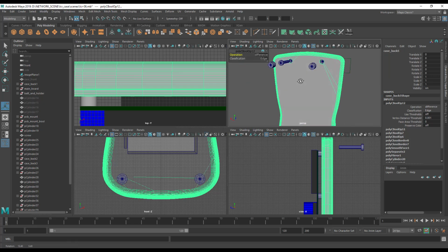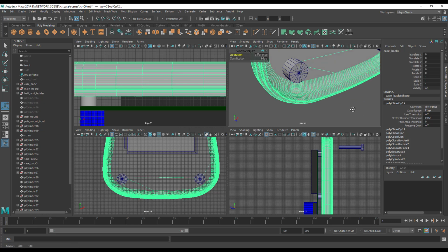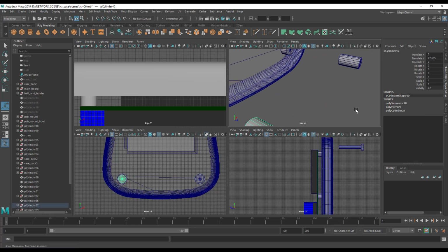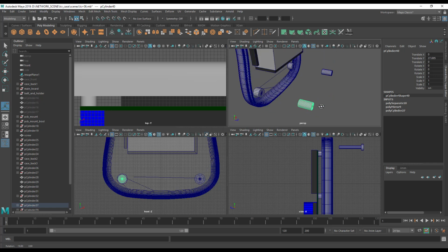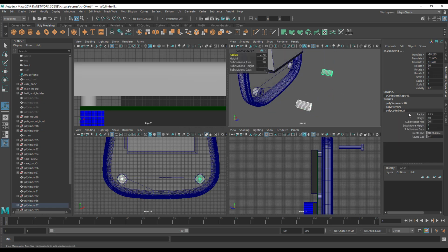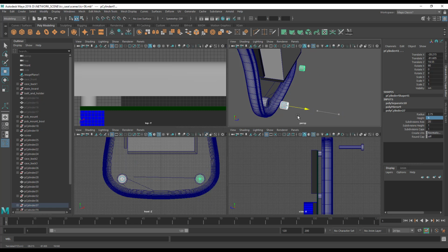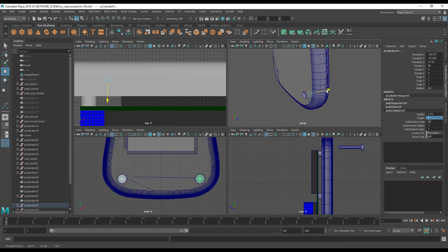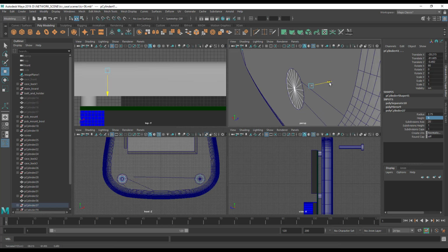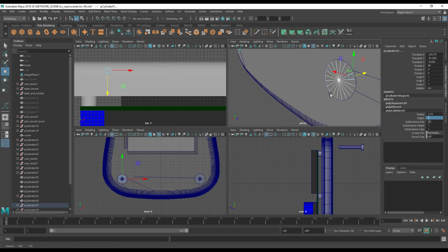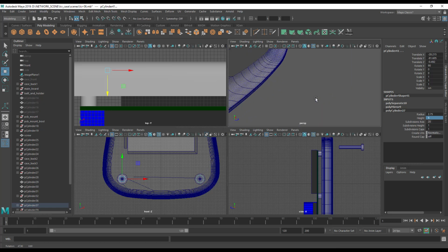So we'll have 2 screws that go in up here, and 2 screws that go in down here, which should fairly well hold the case together. Now, we need those, what do we make them in the end? 5mm, I believe. So let's go 5mm. That way we can shove both of them out here, align them with the back of the case. Now you'll notice I'm not being too careful with this. You don't need to be for this. And these will need to be 2.75, yup, same size.